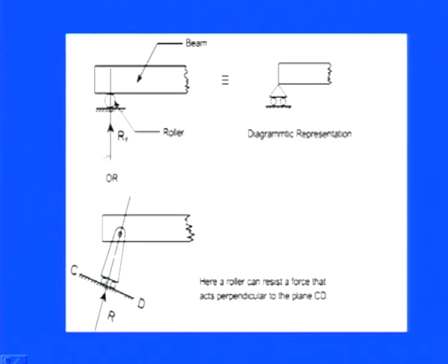So we have a beam, we have a roller, and this reaction is there just to provide the resistance. That is why Ry is there in the vertical direction. It is also shown in a different picture, which is the general representation of a beam on a roller. These rollers always allow the beam to move in the x direction, to either side, according to what load is applied.